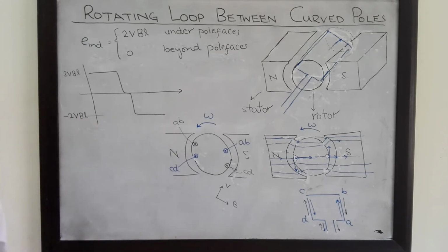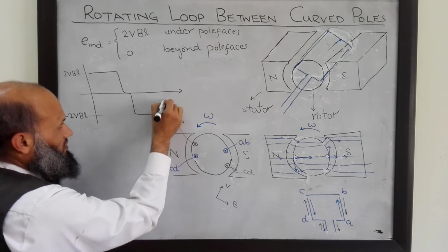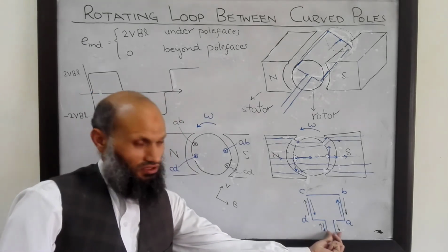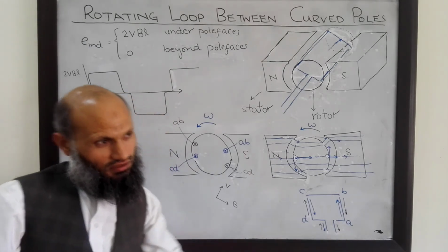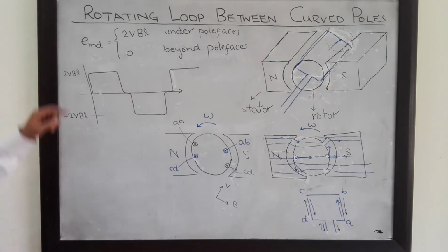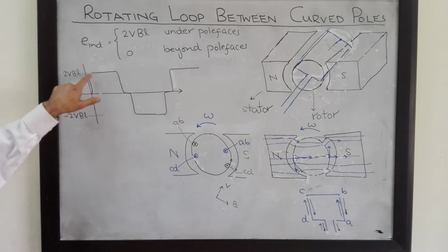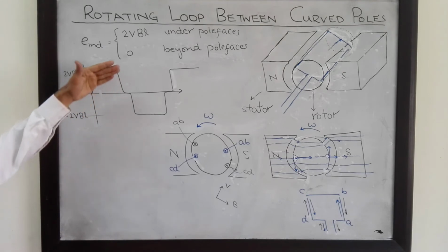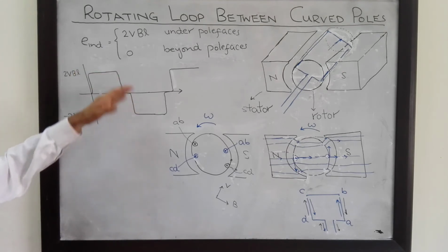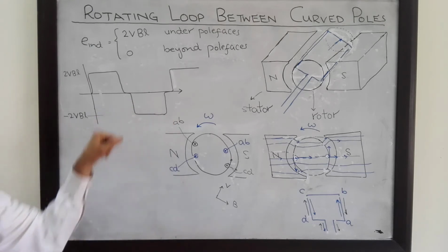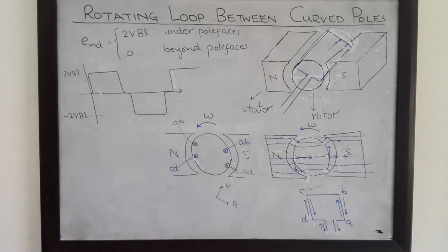And then this cycle repeats itself, and what we see is that the voltage that is available over here is not a DC voltage. It is bidirectional. It is changing its polarity. For a certain time it remains constant. After that it becomes 0, and then it reverses its polarity to become constant again. It is not DC. How can we convert it into a unidirectional voltage?